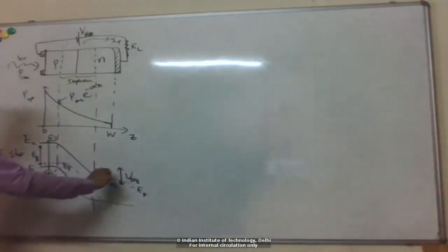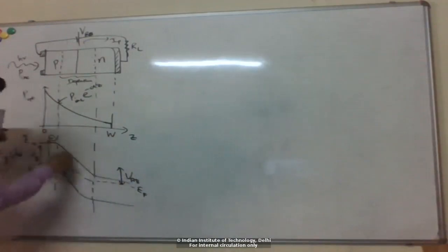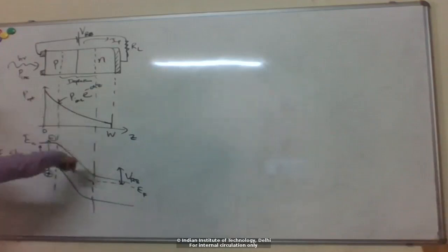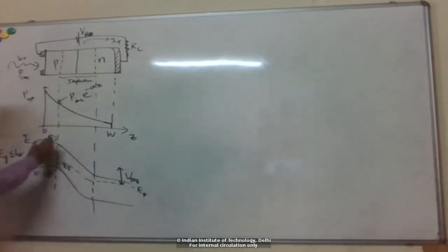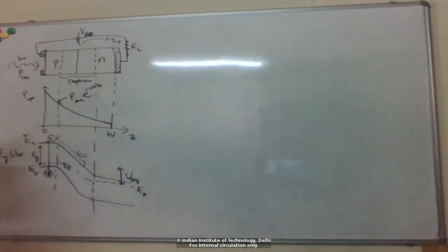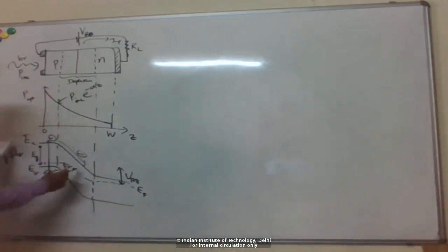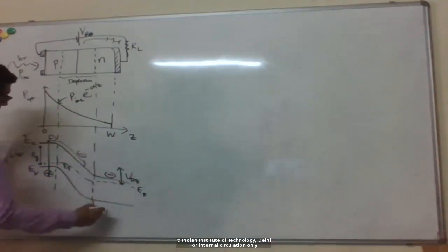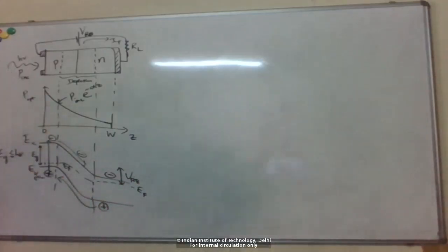Right, so basically you can see that as I apply more reverse bias, this band bending gets more and more severe, right? So this slope becomes larger, which means there's a larger electric field set up in this depletion region. And you can see, as soon as the charge carriers are created, electrons will flow down this potential hill quickly. Okay. So they'll quickly get attracted to the N side and flow out this way, while the holes which are created here will flow like that to the other side.